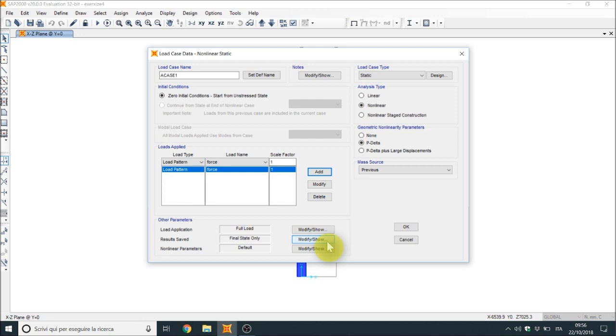But the Newton-Raphson method is not able to give you this softening behavior because it fails when the curve is almost flat. So for the softening behavior you need an arc length. Arc length is a method that searches the solution around an arc of a prescribed length. But these are numerical questions.